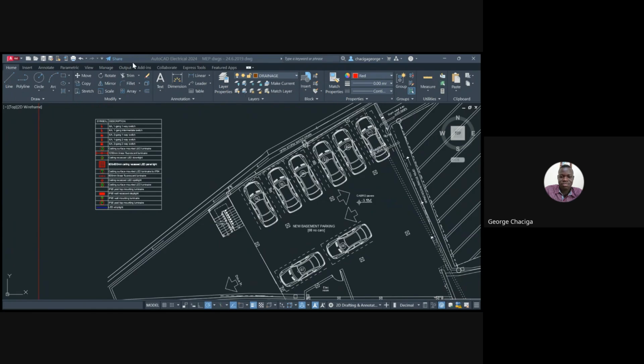You would see the lumens and how it is distributing the light uniformly, which range, all that would give you the perspective on how you're going to space these lights, so that you have uniform lighting and enough lighting based on the application of the room. That I leave to you, because those are considerations that you really do have to research whenever you're doing a design. Okay?